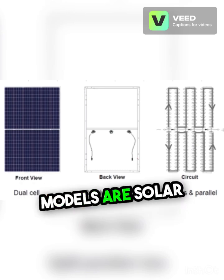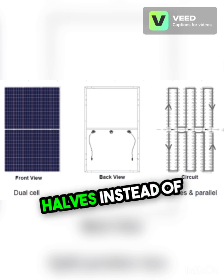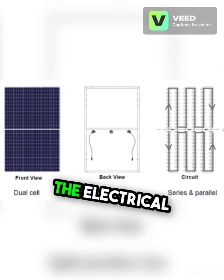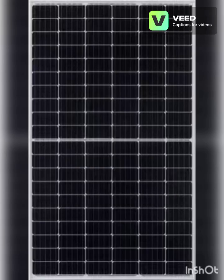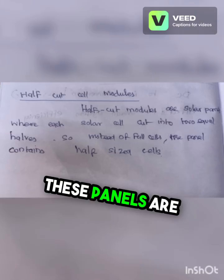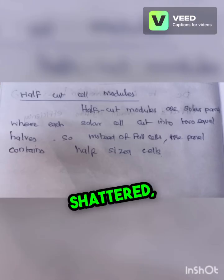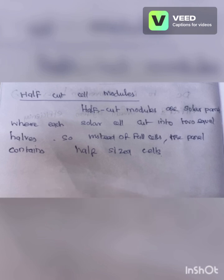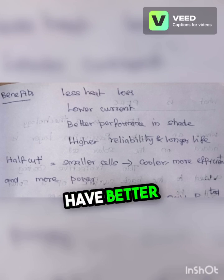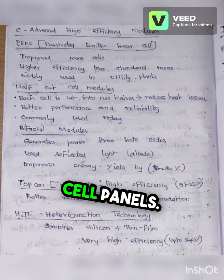Half cut models are solar panels in which each solar cell is cut into two equal halves instead of using full-sized cells. By cutting the cells, the electrical current in each cell becomes lower, which reduces heat loss and improves efficiency. These panels are also divided into two halves, top and bottom. So if one side is shaded, the other can still produce power. Because of this design, half-cut models generate more energy, have better performance in shade, and last longer than traditional full cell panels.